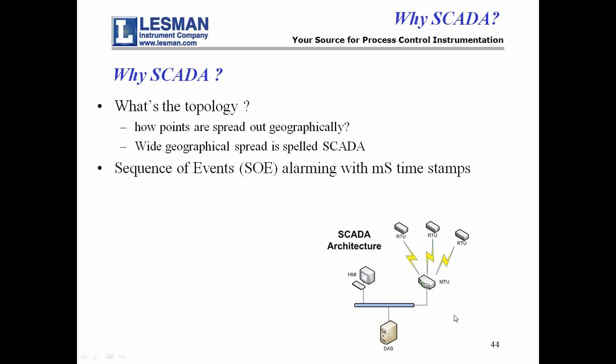The other thing is that there's a particular feature called sequence of events alarming. It usually is associated with a millisecond timestamp so that people can tell exactly what the sequence of alarms were. And that typically is a SCADA feature that isn't always as emphasized in ordinary HMIs.